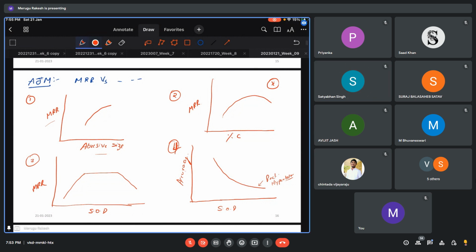Okay. So I just discussed this concept of drag as well as momentum, right? So if I increase the standoff gap, what happens? Which will dominate here? No. See, in this region, since I'm getting an increase in momentum, an increase in MRR, the momentum is higher. It is dominating the drag. So drag happens in this case also, and you are using air here instead of the slurry we used in that case. But here they are more or less equal.